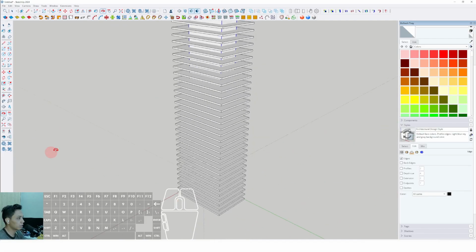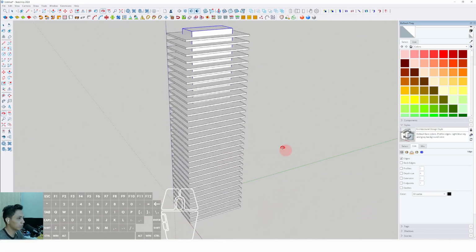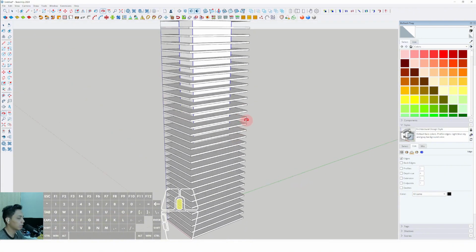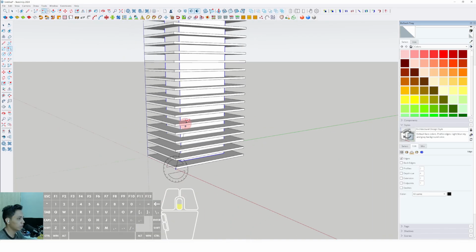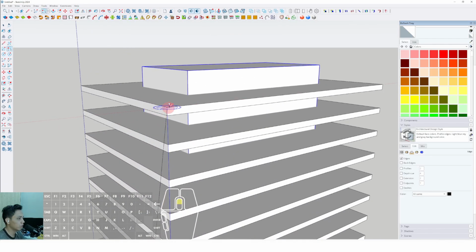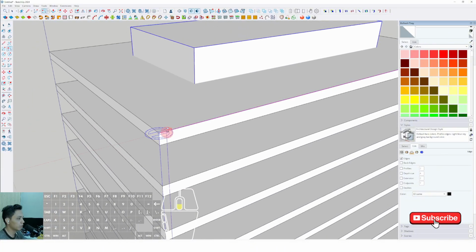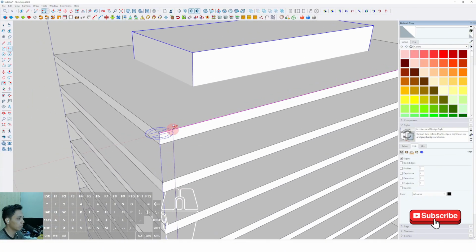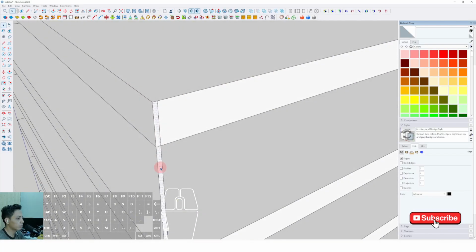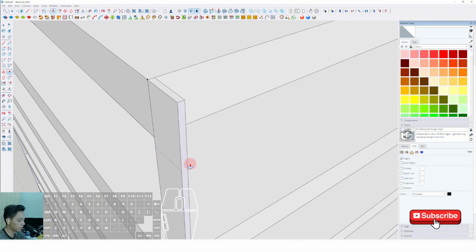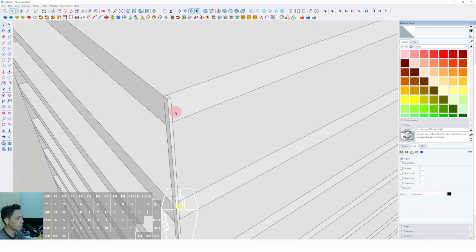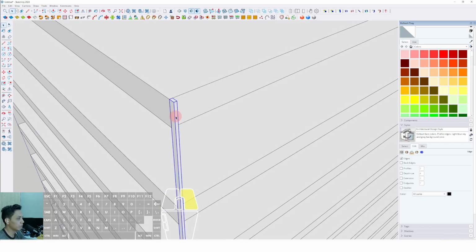Okay, and now we can make the skin. We can make the curtain wall here using the rectangle or rotated rectangle, but I suggest you use the rotated rectangle to make it easy. Click from this point until this point, then direct to the other position right there around 100 millimeter. Then we can click this surface, select push, push it to the front around 200 millimeter, and triple click, right click and make group, and right click and make component, and create.